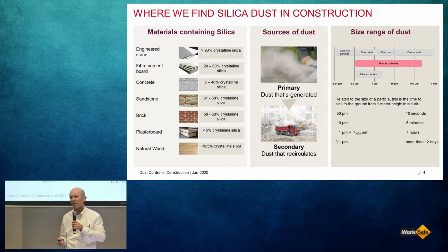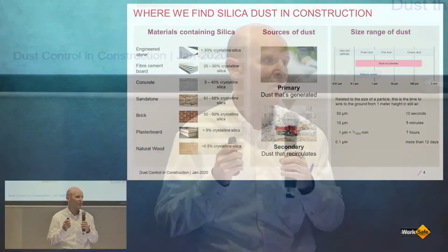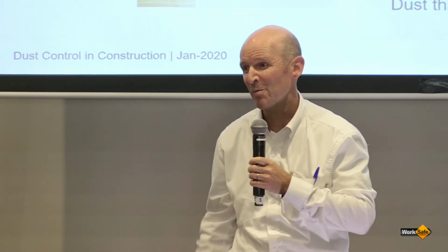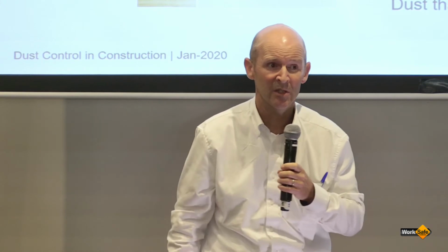Now, those dust particles aren't as reactive as the dust when it was first cut, so it's not quite as dangerous as thought, but it nevertheless is a danger. And that's why in many key building sites, many key builders have actually banned sweeping, and they now insist on cleanup by vacuum cleaners, because blowing anything is just redisturbing that hazardous dust for somebody else to ingest.